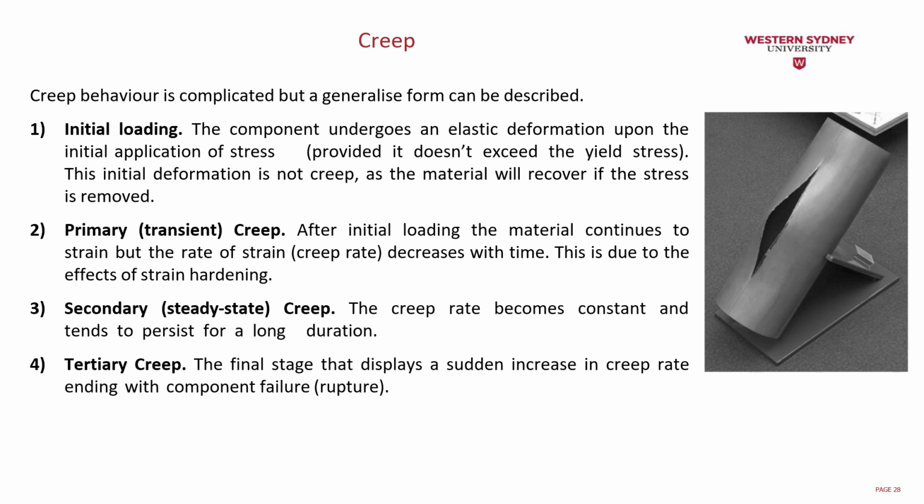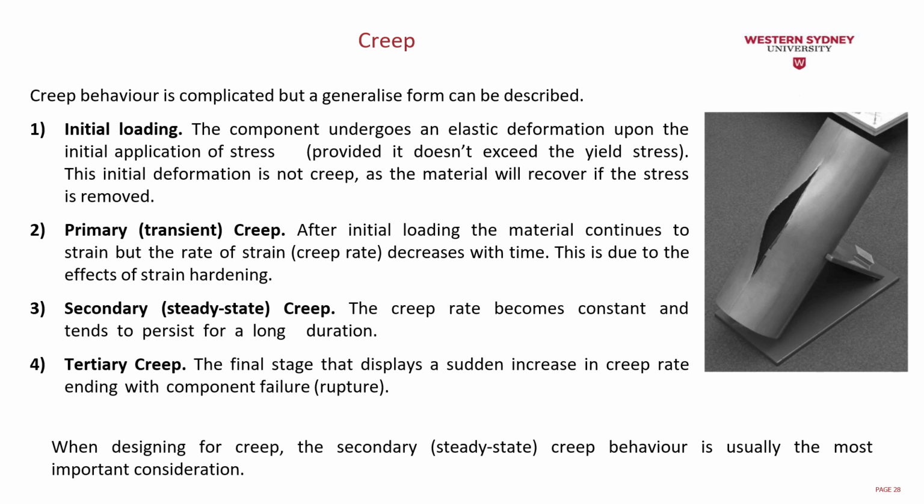We have the tertiary creep, the final stage, which displays a sudden increase in the creep rate, ending with the component failure, which is the rupture process. So when designing for creep, the secondary or steady state creep behavior is usually the most important consideration for us.